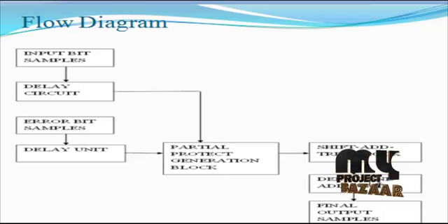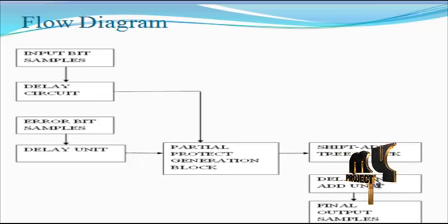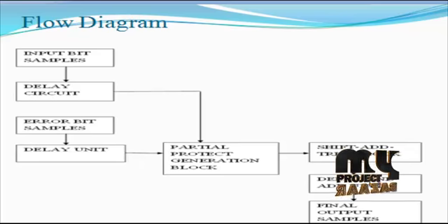The delay element is mainly a D flip-flop register element. The adder element mainly focuses on the LSB and MSB positions of the shift add architecture result, which is applied to the delay and adder unit elements. The final output samples are mainly based on the synthesis and simulation results. The simulation results are passed as binary results, and the synthesis report mainly focuses on satisfying the parameter results for our architecture.